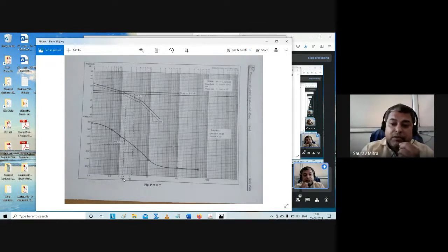Now in the phase formula, you put that 1.4 radian per second, and you will find that at omega GC, 1.4 radian per second, the system phase will be minus 165 degrees. What you have to say is that phase margin is found at omega GC, and phase margin is found to be 15 degrees above minus 180. So here it is written very faint, phase margin is plus 15 degrees. Okay, so phase margin is plus 15 degrees, or 15 degrees above the minus 180 line. Hence the system is stable from the phase margin point of view.